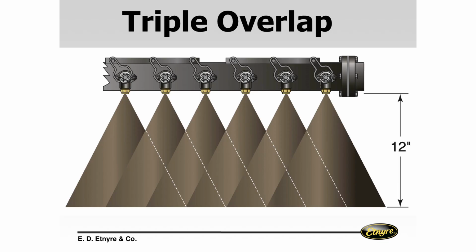So there's some things we've got to look at. We really want 12 inches from the bottom of our nozzle to the ground. That's where we want to set. We don't want part of our spray bar drooped all the way to the ground, part of it way up in the air. You'll get the right rate, but it won't be uniform across the road. So we want to make that setting correctly.